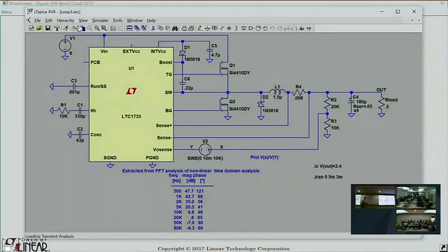But it's easier than that. Usually the transconductance is equal to the maximum current output of the power supply, because typically you have a 1 volt active region here, so 0 to 1 volt is 0 to full scale current. So if you have a 5 amp power supply, the transconductance is usually 5. But all of that is a transconductance.